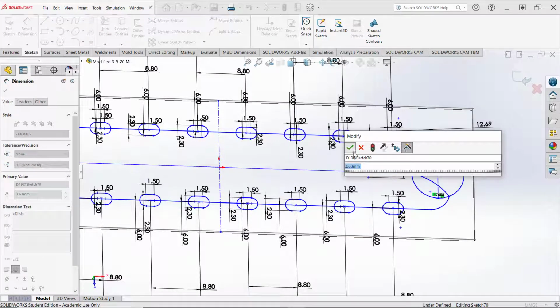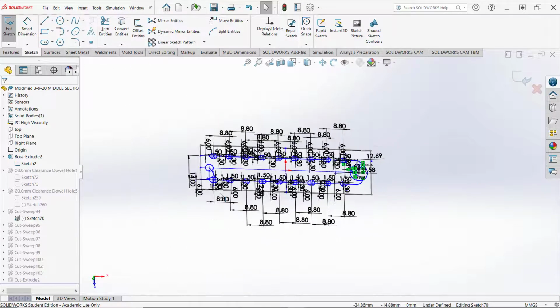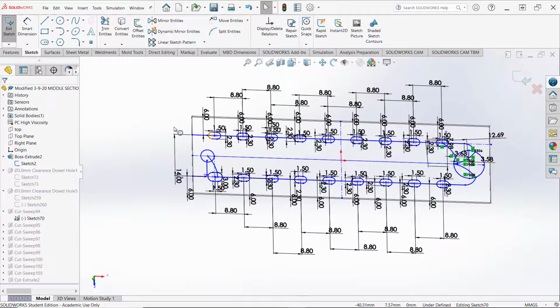Right now, of course, I can't find one when I want to look for it, but there are some dimensions in here that don't make logical sense to me. If I can't measure it out on the shop floor, or at least in inspection with a precision measuring machine, I can't manufacture it. So we try to use dimensions that make sense.